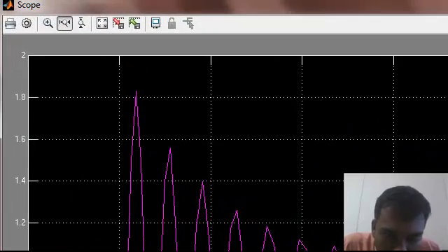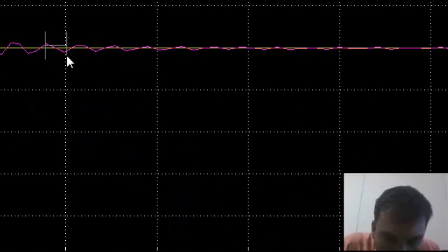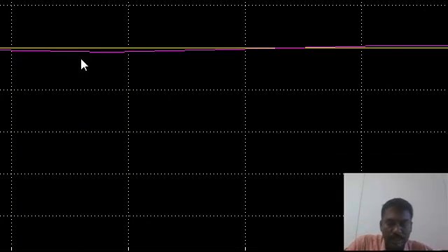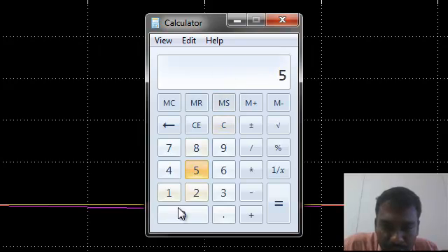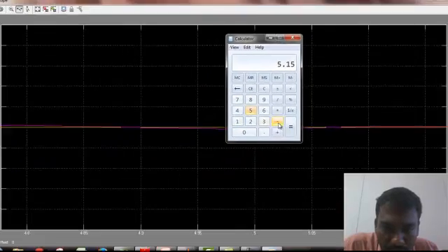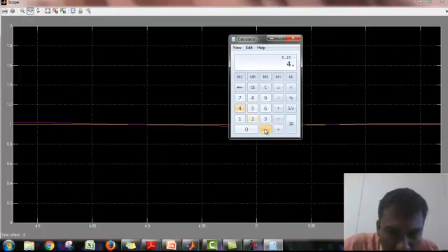So I'm going to zoom this x-axis, selecting from this point to this point, as I said in the PPT. So what's the difference coming? This is called the ultimate time period. 4.8 to 5.15, so 5.15 minus 4.8, yeah, 0.35 is coming. That's the time period, 0.35.